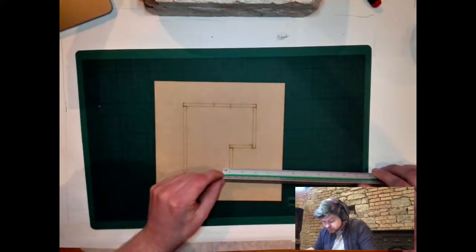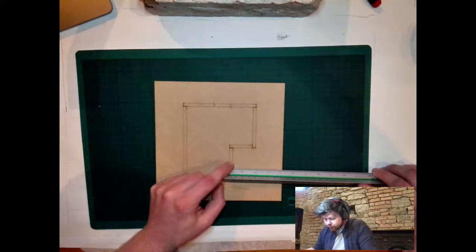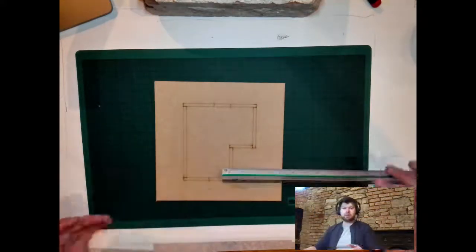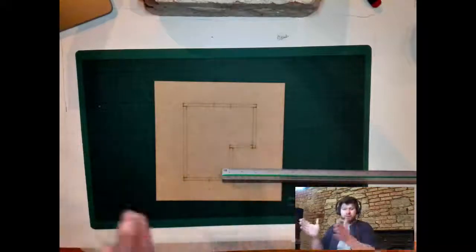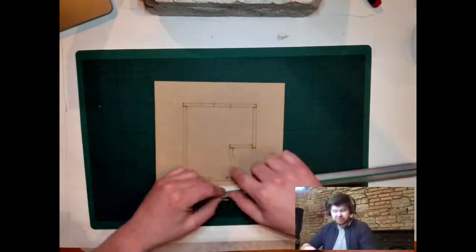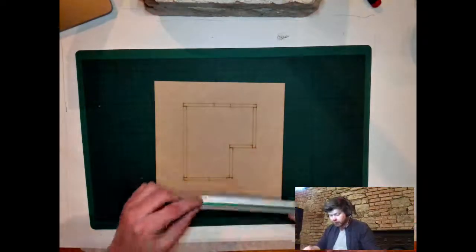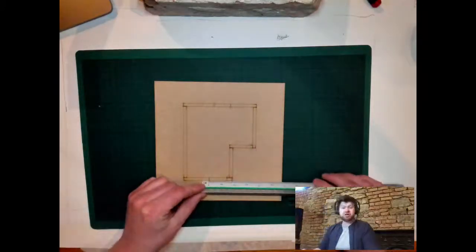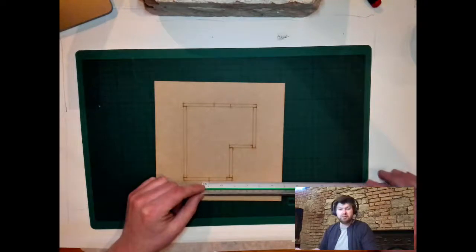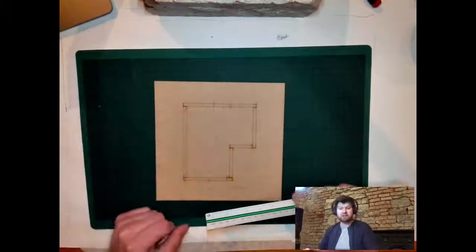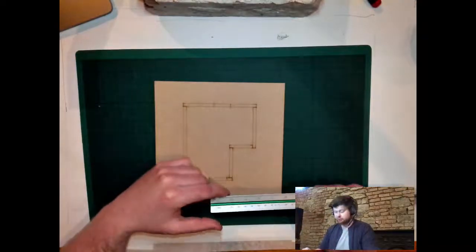that is 0.1 of a meter or 100 millimeters. So yeah, that would be correct. So if in real life the wall was 100 millimeters, and if it's scaled down at 1:25, then it's this size on the model. For example, I could measure the door. So that says it's 0.7 of a meter or 700 millimeters, and I'm using this scale here to automatically understand the measurements of what it would be like in real life.